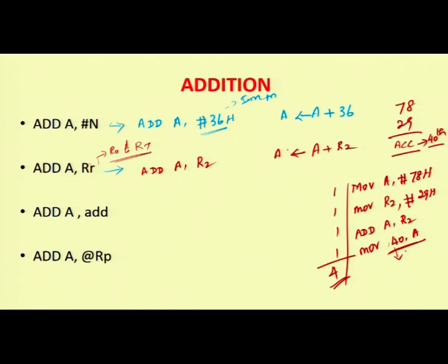As per the previous discussion, the clock frequency generated by the 8051 is divided by 12, and that will be considered as one pulse duration. Based on that you can calculate the corresponding time: 4 into, suppose, 1.085 microseconds. So, this is the timing it will take to execute these 4 instructions. Okay. The another one is via the memory.